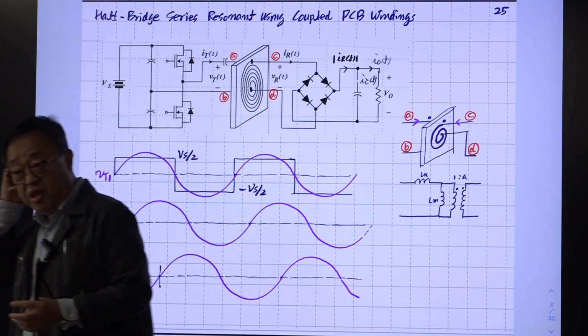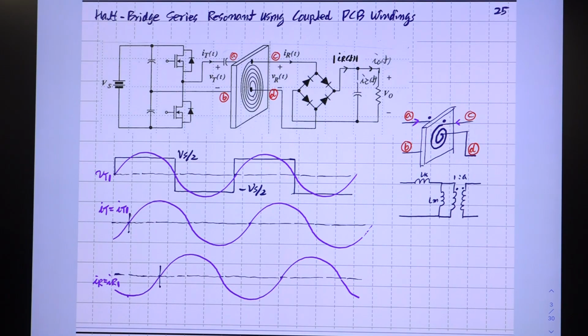This situation is very similar to the situation they are having in the industries. Okay, for the low profile design, they squeeze everything into this narrow height. They have a planar type of transformer and the size is limited. So they try a very dense transformer and measure the values of this, and they select the switching frequencies to provide a good operational region for this converter. Okay, so they don't have a design procedure actually, but to have a proper operation, they should understand everything, including the design process.